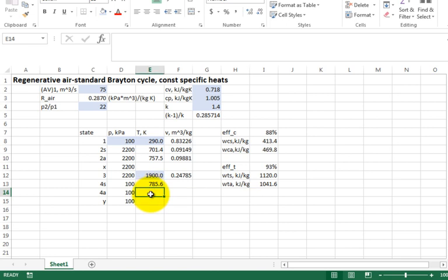So now we can actually calculate the exit temperature to be this minus this divided by the specific heat constant pressure because I want it back in temperature. So it comes out a little warmer. It comes out 863 versus 785. See that? You can play the same thing. Let's say it's 99.9% isentropic efficiency. Now those two match really well, don't they? So let's put it back at the 93% isentropic efficiency for our problem. Maybe I color code this and say, yeah, that was a given, that was a given into my problem statement.